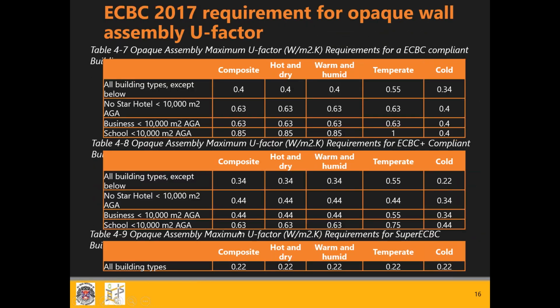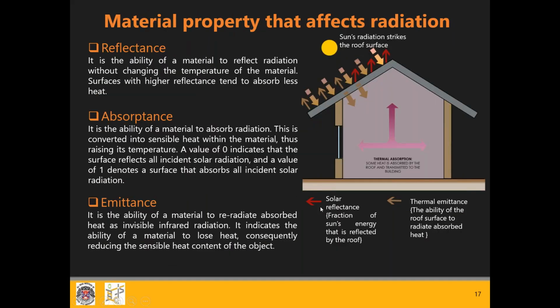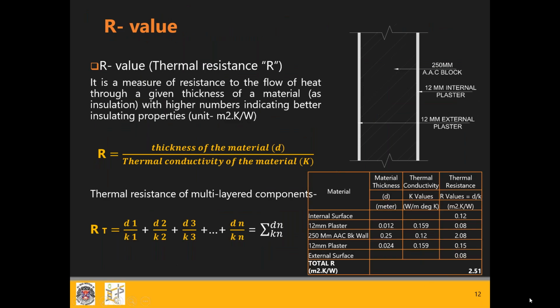Okay. So I hope how to identify and how to calculate your U value for your roof and your wall is clear. Now moving forward, if you have a section, you can quickly go to an Excel sheet, do the small calculation that was provided, see that my total R value is this, and then divide 1 by that to get my U value.